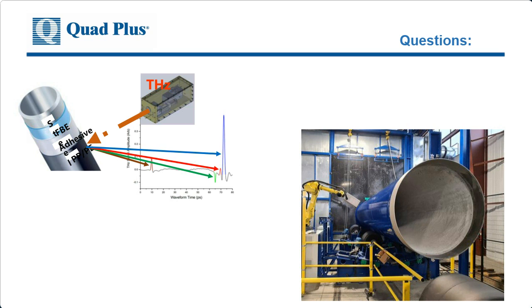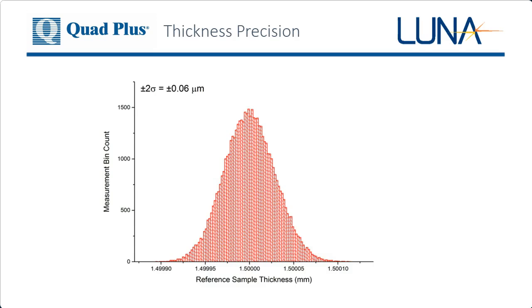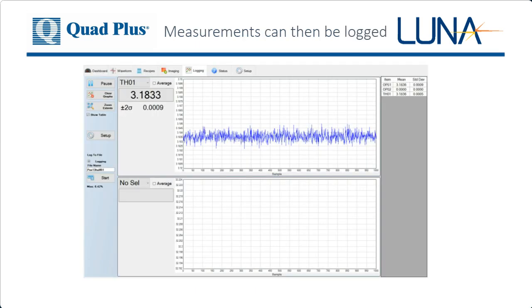Can we know the error tolerance? Earl, I think you kind of touched on that, but can you go back over that maybe? Yeah, sure. I did show a slide on that. I think I can bring that up. So this was a long-term measurement. A better one would probably be the slide before it, where I was measuring at a kilohertz. I'm measuring this 3 millimeter thick object, and I'm doing it to less than a micron. Now this is of course a very ideal case.